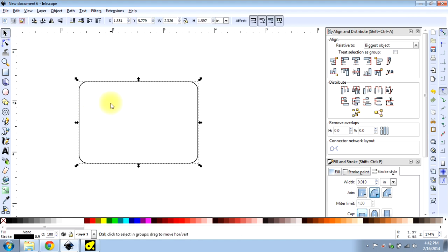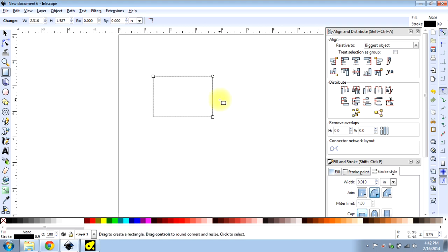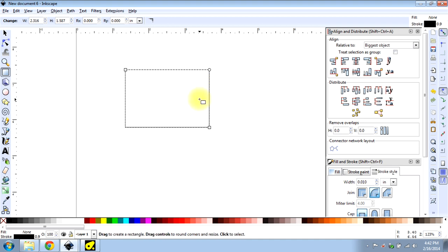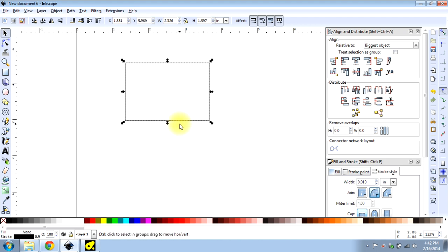This is the tabs and sockets method, but it's also the mortise and tenon, I would call it as a carpenter. So we're going to start with a box with sharp corners. And again, this is going to get a little ugly because of the line thickness. When you're doing this at that 0.001 line thickness, it's going to be perfect, and it's going to make so much more sense and look so much better. But you cannot do this thick and then convert it to 0 at the end because your dimensions are going to be funny.